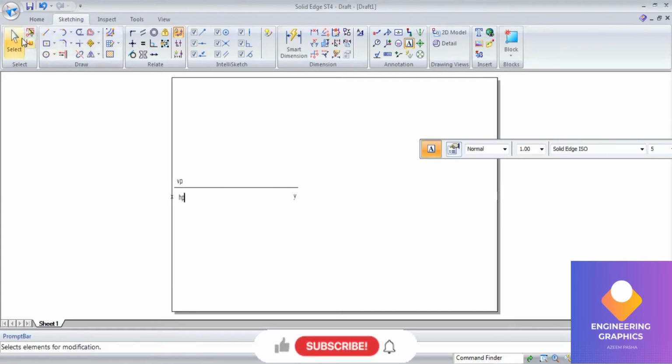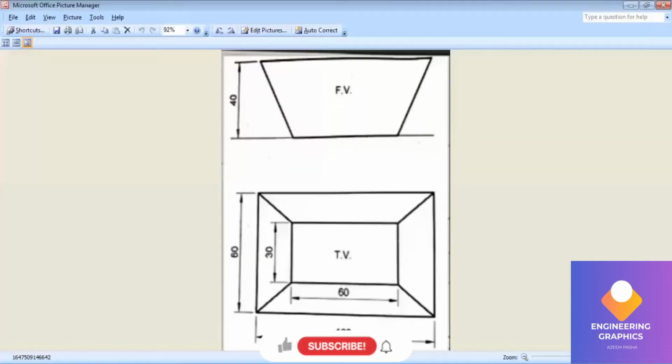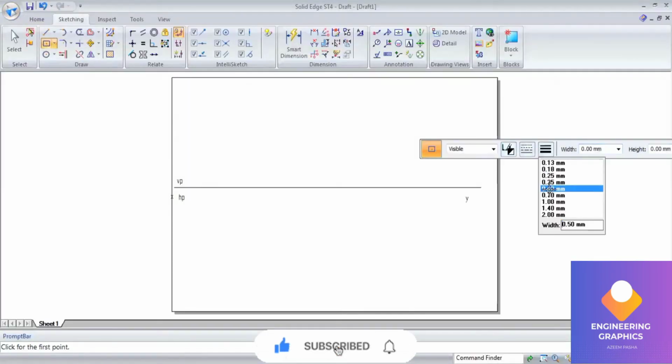I'll be constructing the same top and front view with the dimensions here, and then I'm going to draw the development of the square tray. Okay, here development of the square tray is easy. You can see first I have to construct a rectangle, dimension 100 into 60. Okay, I will take thicker here, 100 into 60 rectangle.